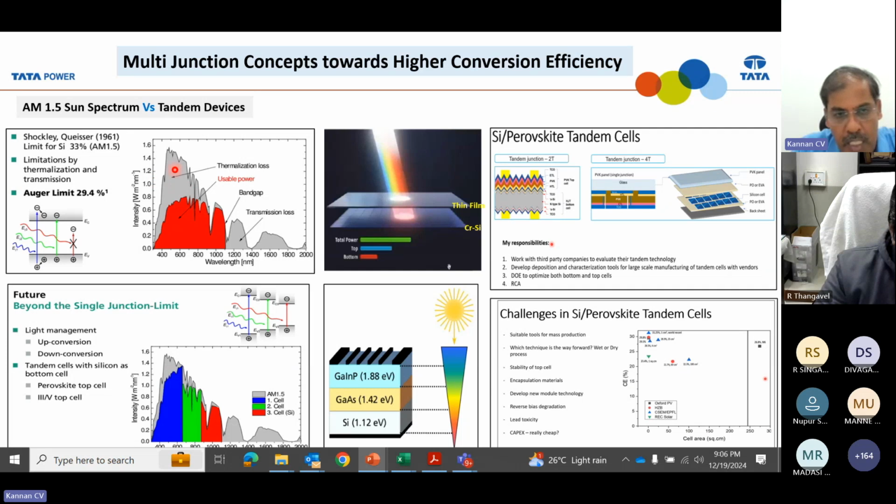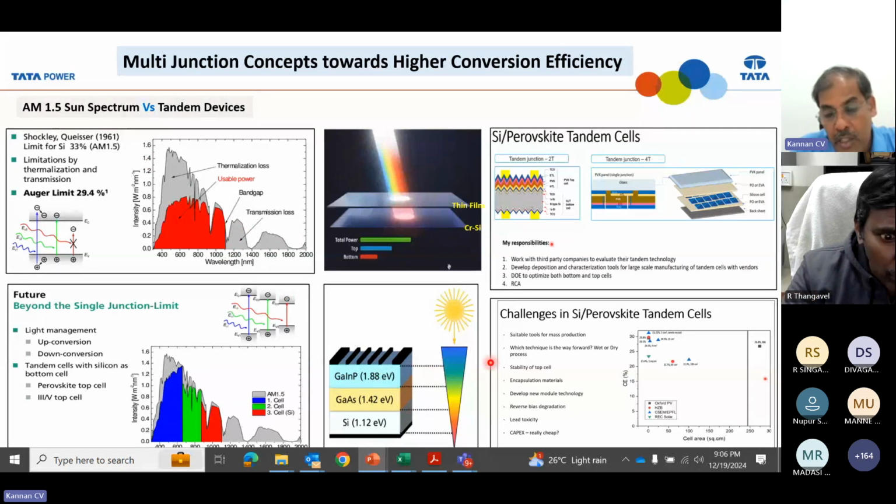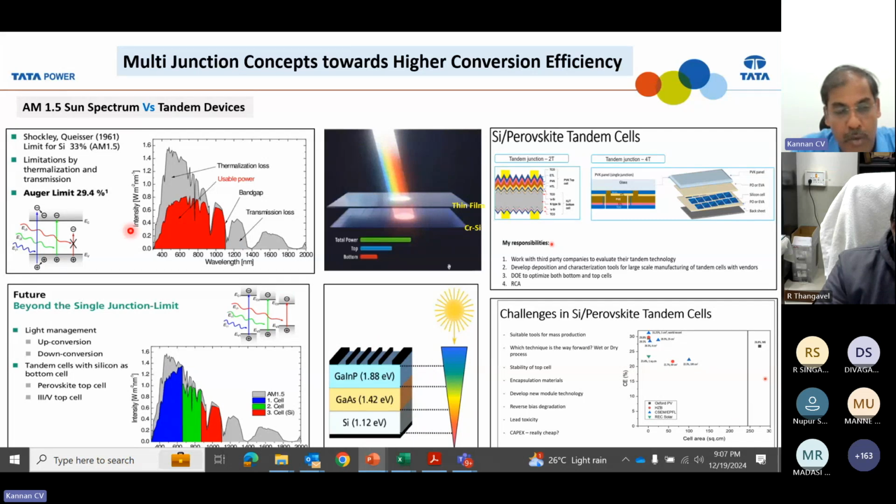The amount of sunlight in the IR is relatively low. So a major portion of the sunlight will be converted from photon energy into electrical energy, so the efficiency, which right now is about 25, 26%, will go to 30, 35%, and if you add 3 junctions or 4 junctions, 35 will become 40, 45 also. This is the way the industry is working: instead of going with the single junction solar cell, they are going with the multi-junction solar cell, called a tandem-based solar cell.